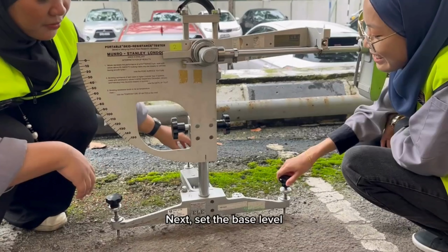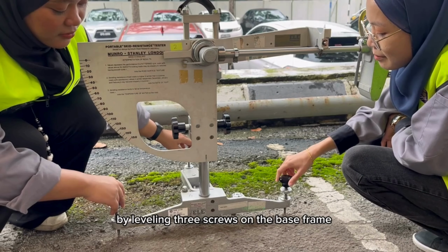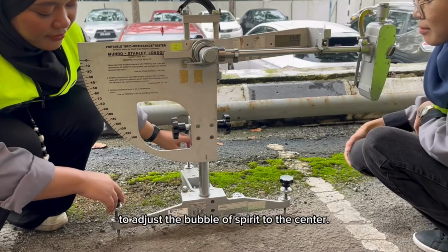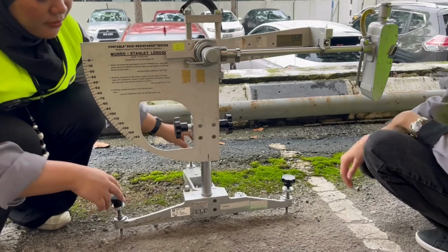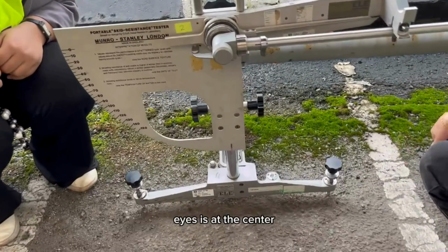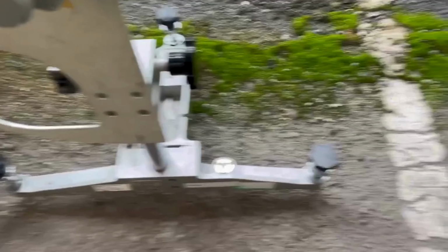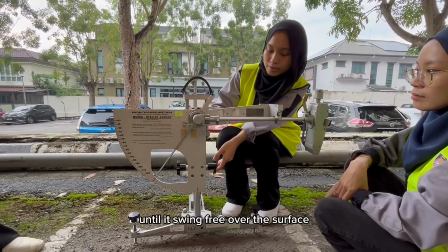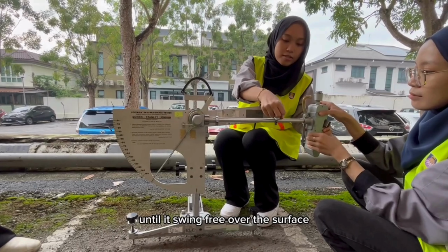Next, set the base level by leveling 3 screws on the base frame to adjust the spirit bubble to the center. Make sure the bubble level with a circular bullseye is at the center. Next, loosen the locking knob till it swings free over the surface.